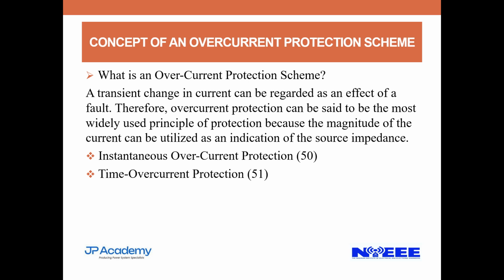So instantaneous protection, we cannot use it for direct online because it will trip, unless we increase our set point, which could damage our motor. Now, this is the basic difference between instantaneous protection and time overcurrent protection. And as I mentioned earlier, we have other protections. We have the differential and the distance protection, although we'll be focusing on the overcurrent protection scheme in this webinar.